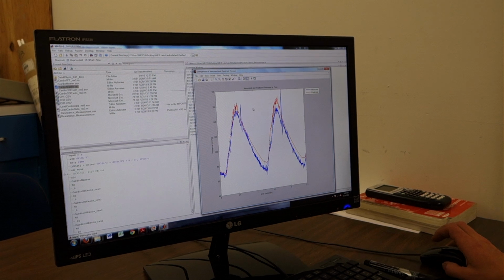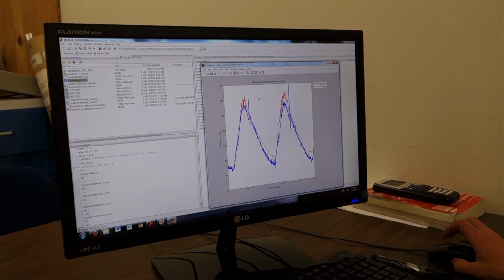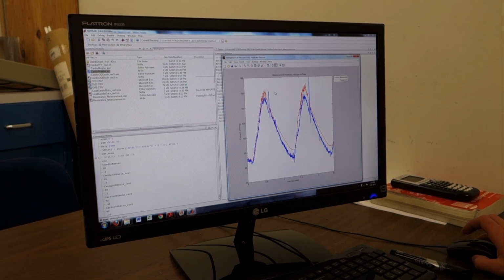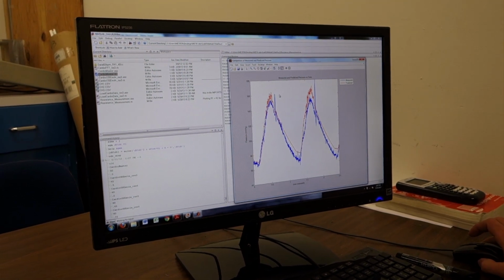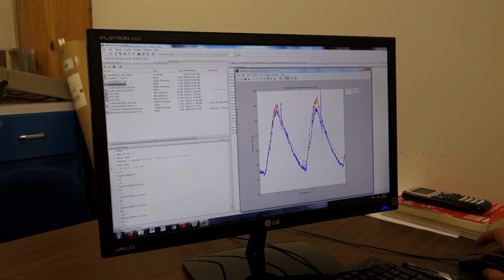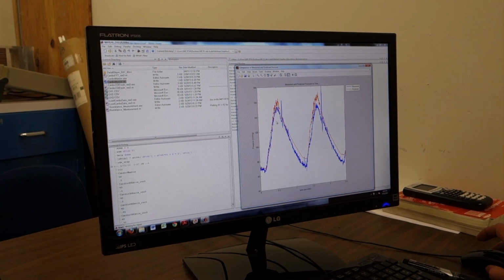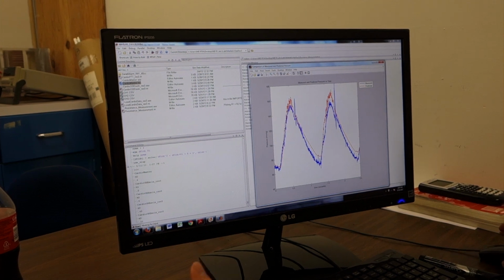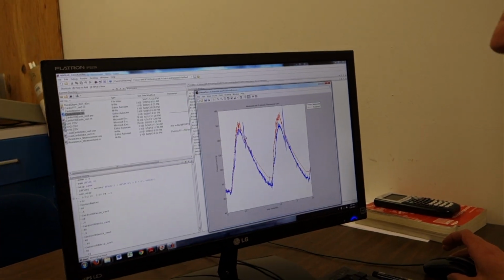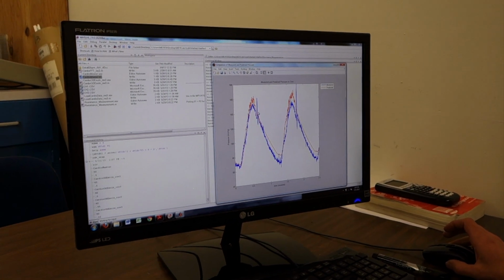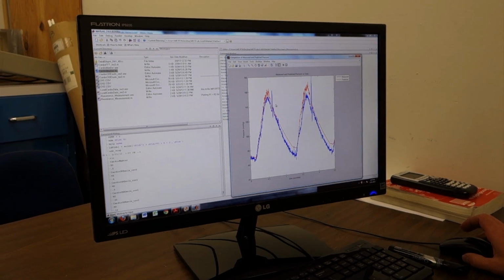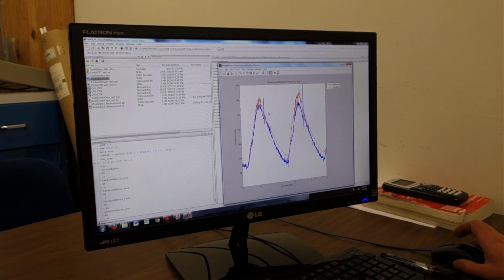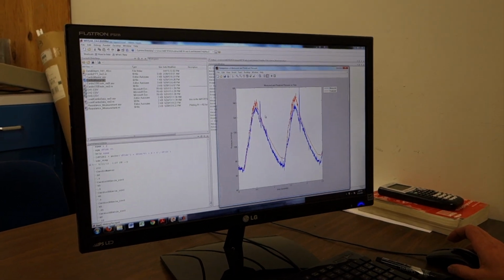But for all intents and purposes, we have modeled the pressure in this iliac bifurcation via modeling the rest of the cardiovascular system as resistances and capacitances fairly well. We have modeled the effect of the dicrotic notch. We've modeled the amplitude pretty well. We've modeled the period of loading pretty well. So now we have a device that simulates the effect of the systemic cardiovascular system that we can use to test our stent graft and to try to take measurements on the stresses developed in the stent graft and maybe fatigue life of the device.